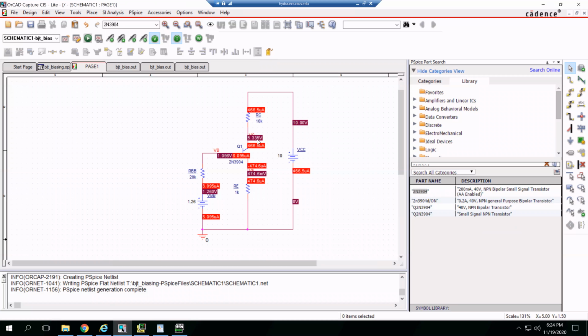So in terms of the voltage and current, that's logical, right? The more current you have going through your collector resistor, the bigger the voltage drop you're going to have across this resistor, and the smaller voltage you'll have on your collector. So the fact that the current went down, that should tell you there's a smaller voltage drop across this resistor and a bigger voltage here.